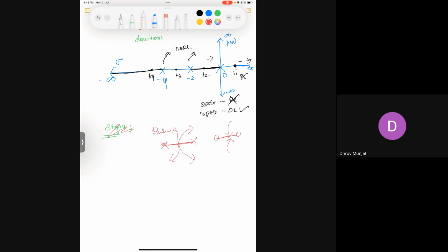So this is how changing the k value will affect the loci of your system. It's proven based on the system's nature, and by changing the k value, this is how the system behaves. If there is 1 zero and 1 pole, then there might be a branch or there might not be a branch. So you cannot say whether the root loci exists here or not.